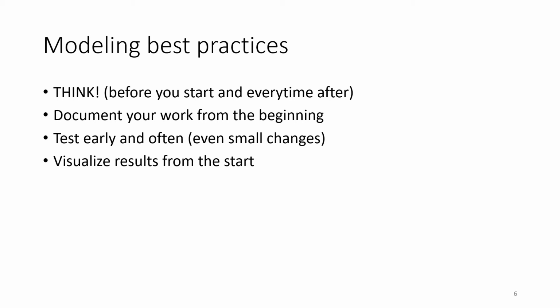And documentation goes beyond just storing all the files you have been using, right? Do a consistent naming of files, meaningful names. Write down what you did between the different simulation runs, because as I said, you will start with something and modify this one, and then modify this one again. So keep in mind what you change from time to time, what the effect was, so that even after weeks of work, you still remember what you did.